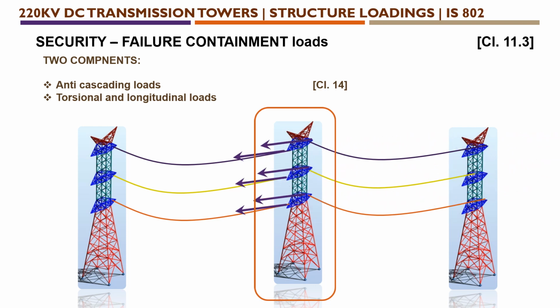Suppose due to the right hand side conductor sag, there is a static tension which pulls toward the left hand side. The arrows showing on the left hand side are the static tension applied for the conductor on the right hand side. Similarly, for the left hand side conductor sag tensions, we need to apply a pull towards the right hand side, shown in red arrows.